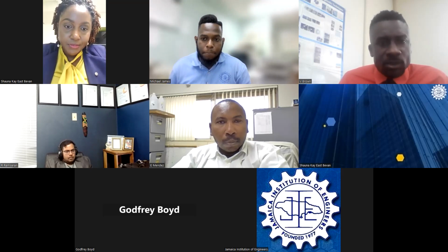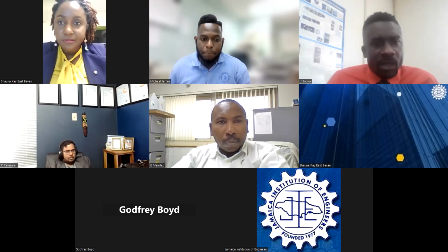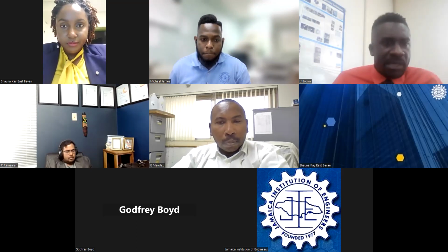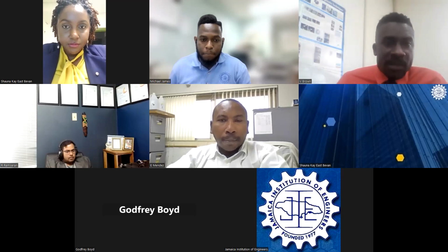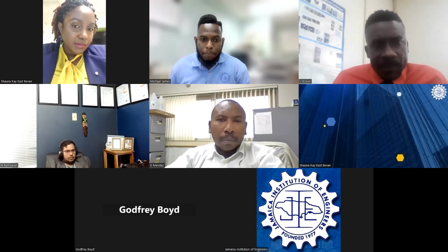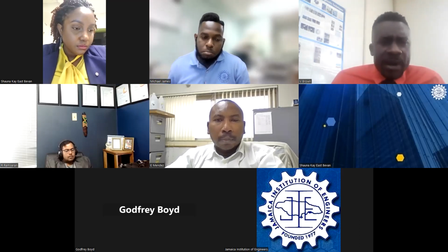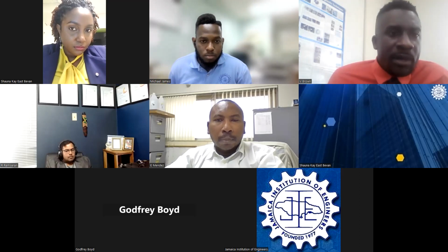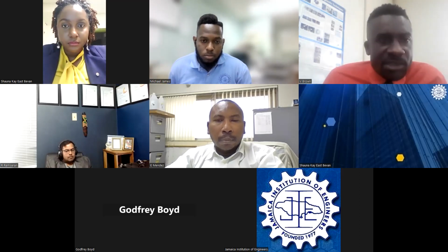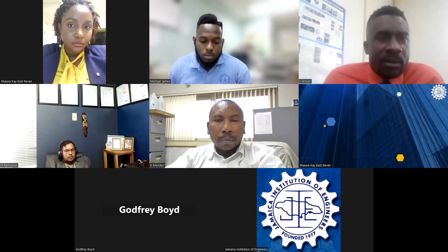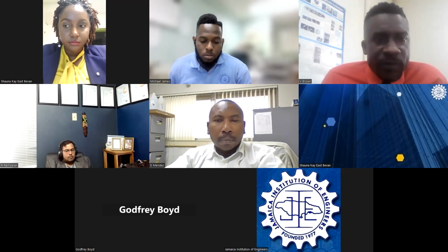Okay. Also, our next point for motor basic maintenance: if you can't afford those MC Max test sets, many companies are leasing them now. They lease it, they train you to use it. And you use a regular multimeter, a regular megger, to do your insulation checks and write your figures down, train them, and you can see the difference happening.